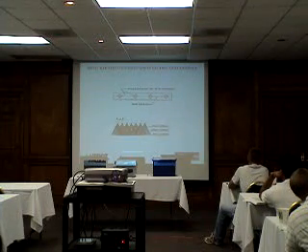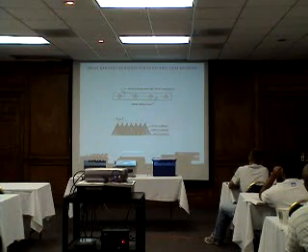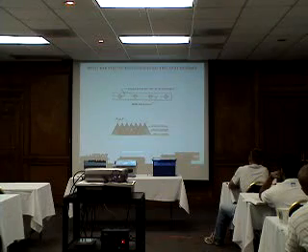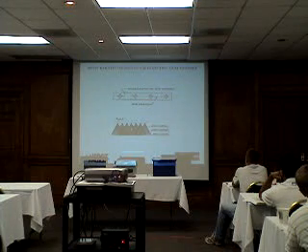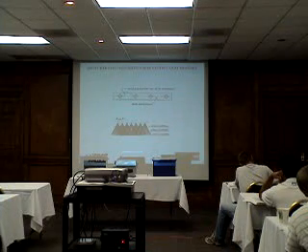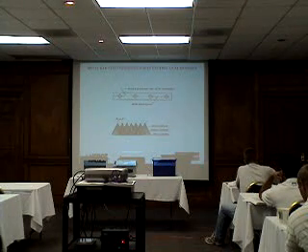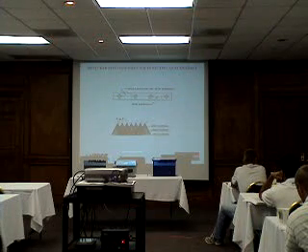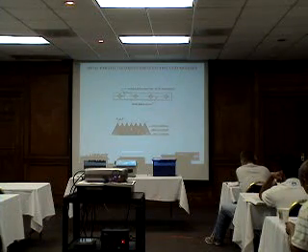The spray bar system is a series of nozzles that are set at a certain angle. As you can see here, these nozzles are approximately 4 inches apart, and they're set at different angles, depending on the type of coverage you want to make. You've got to make sure that these things are in good working condition, set at the proper angle, and that they are the right type of nozzle for the application that you're going to be using.